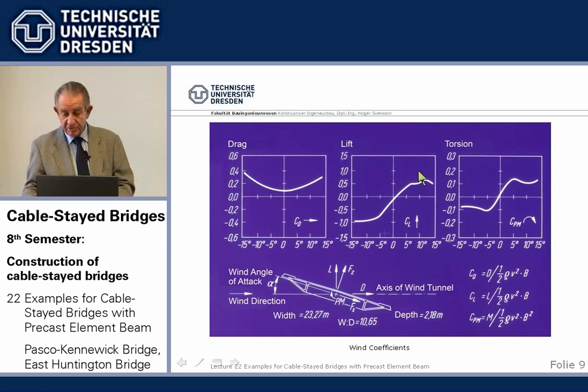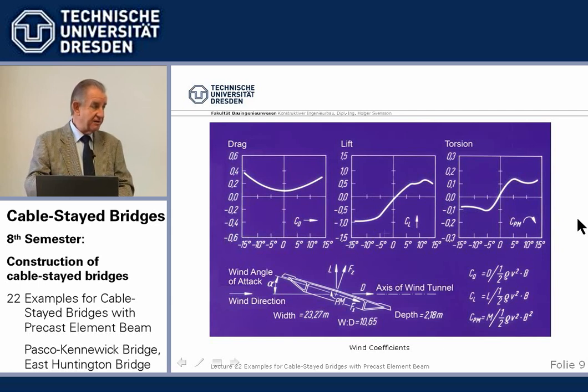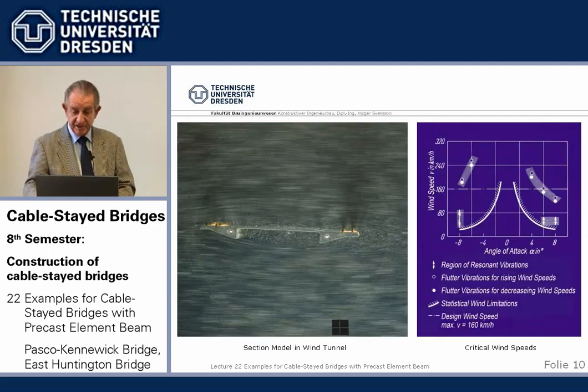It's pretty normal, nothing spectacular, but we need, of course, these values to calculate the stresses or the moments in the beam from wind transversely. So wind tunnel tests were done. This is a visualization, I think, with smoke. This is our model in the wind tunnel, and we can see here vortices. It's an open cross-section, and we see the vortices forming here.